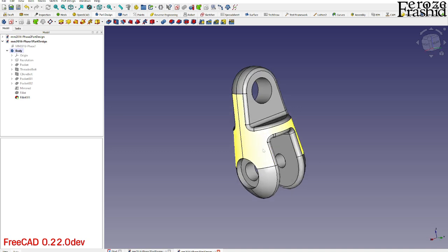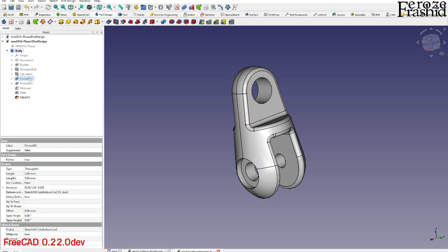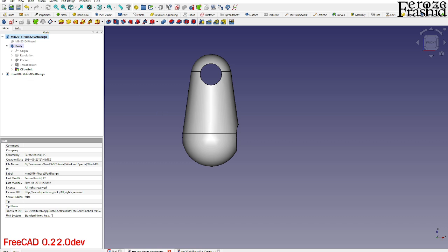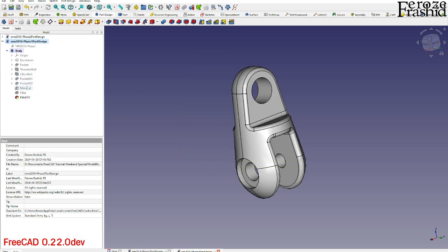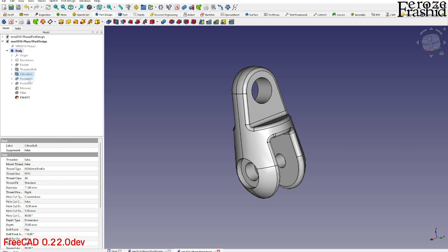Save it. And phase 2, as I mentioned, we will have to go back some distance and then update these cut profiles. Actually, we'll have to go back up to this Pocket001, and that's why I saved it, so we don't have anything after the C bore. So after the C bore here, we'll have to change everything for phase 2.